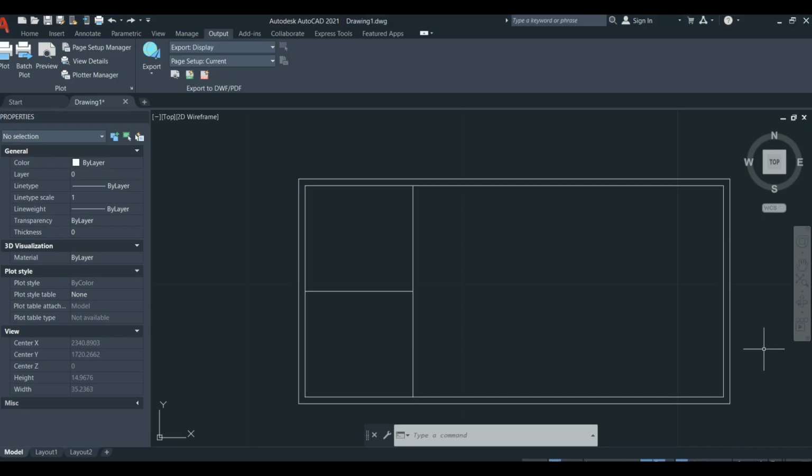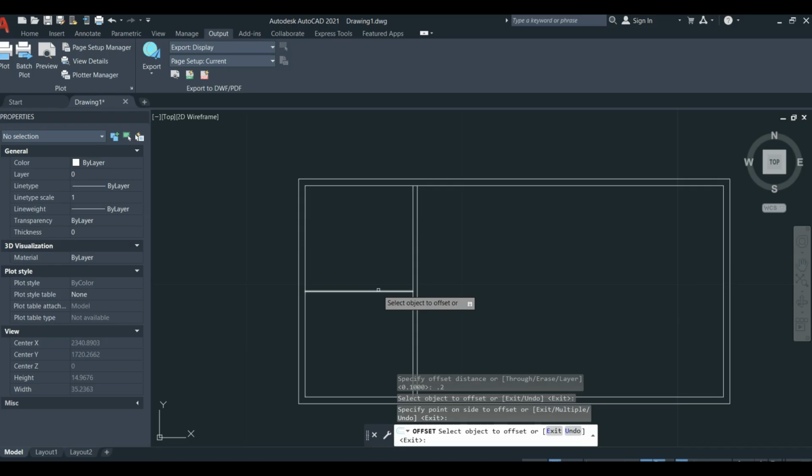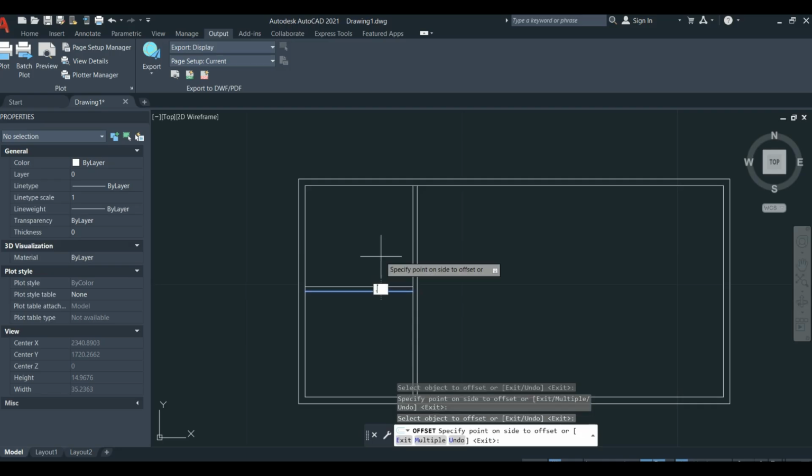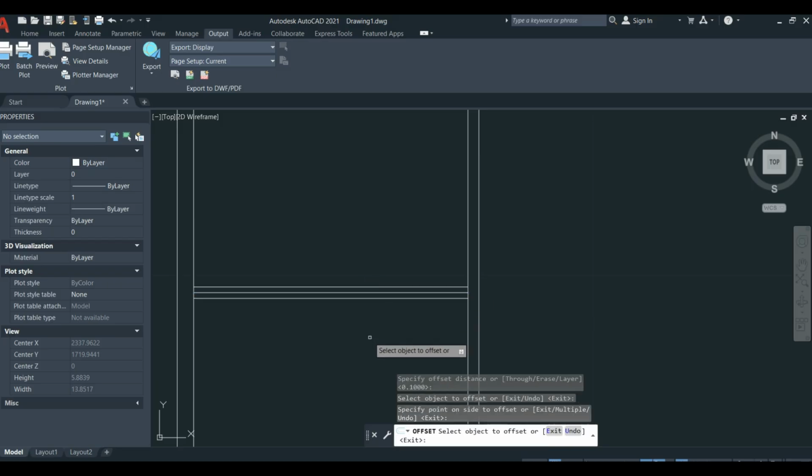Now it's time to dedicate thickness to inner walls, and actually I want to give them about 20 centimeters by using offset, and I want to use spaces from the bedrooms, 10 centimeters from the upper one and 10 centimeters from the other one, to make some equal places for any occupation of these bedrooms.